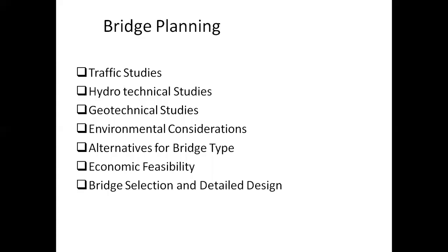So bridge planning, this is what we are discussing. Before planning any bridge, there will be a few studies. First one is traffic studies, hydrotechnical studies, which relate to water. And next one, geotechnical studies, which relate to soil condition, and environmental consideration.